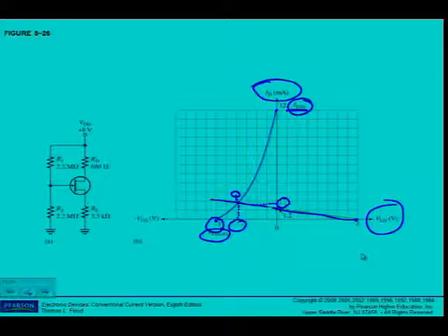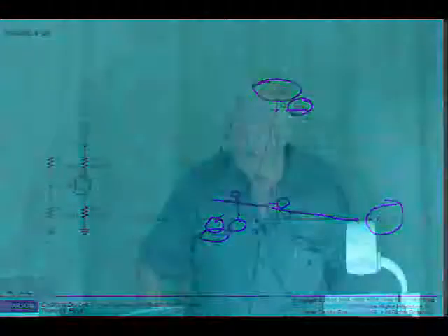So it's not one block that's been used, it's 2 blocks for each voltage. So make sure that you have a look, or even make sure that you choose a correct scale so that you can write the correct values down. Alright, that is the graphical analysis of a voltage divider bias JFET.